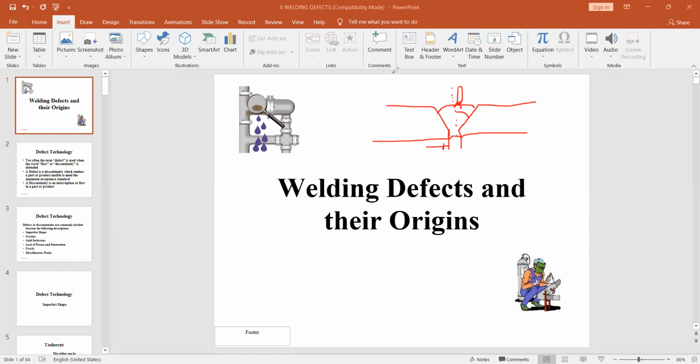In WPS, we get information about the current range we need to use for that particular weld, the voltage range, preheat temperature requirement, interpass temperature requirement, and electrode traveling speed. The weld preparation, bevel angle, root face, root gap, electrode size and type of electrodes are also there. So we have to do welding as per WPS requirements. If you are doing welding as per WPS, there are very little chances of defects occurring in the weld.